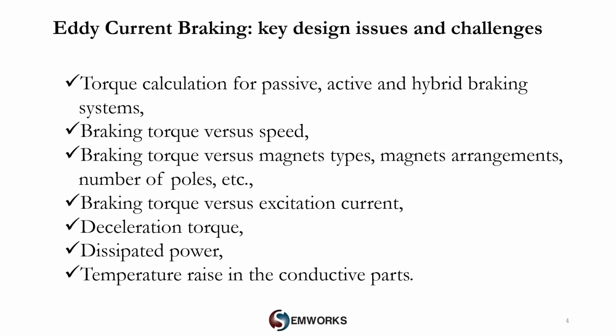In the eddy braking system, the mechanical energy is converted into ohmic losses dissipated in the moving parts. This power has to be estimated, as well as the generated heat caused by these losses. Overall, these are the main quantities a designer has to evaluate before creating a prototype of an eddy current braking system.